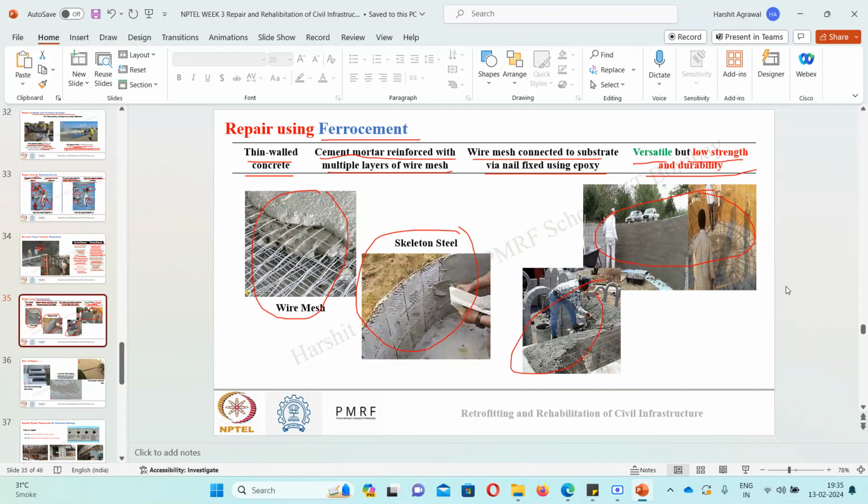Then this will be micro concreting we are using, right? In this case we can use micro concreting or a slurry kind of material also. Polymer concrete, anything. Like in grouting, we are using slurry which can flow. Here the slurry may not need to be that low viscosity. It may have a low viscosity such that it can just coat the wire mesh properly.